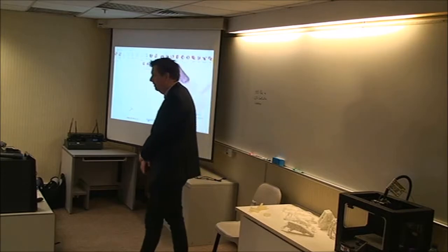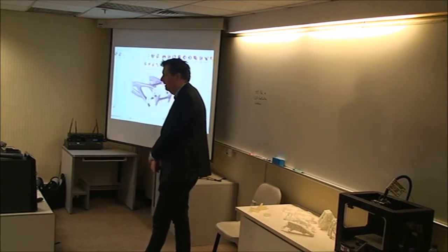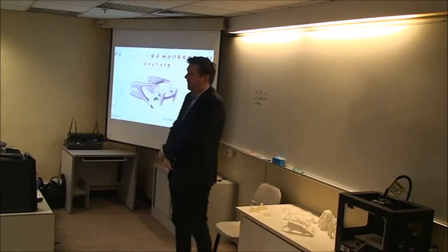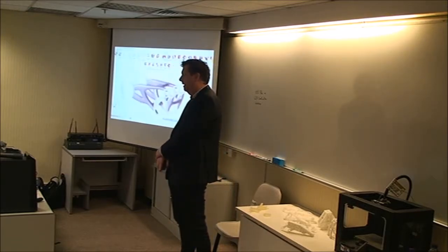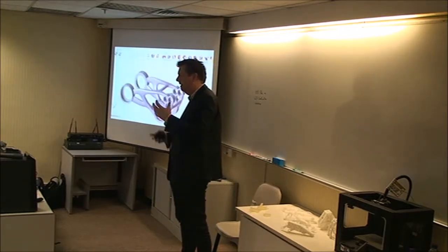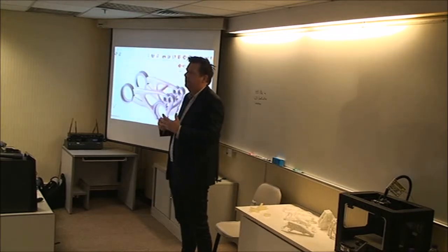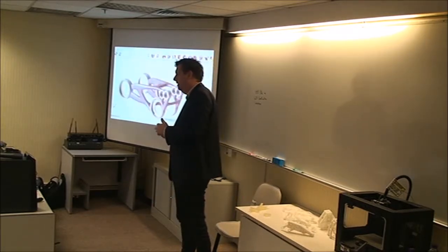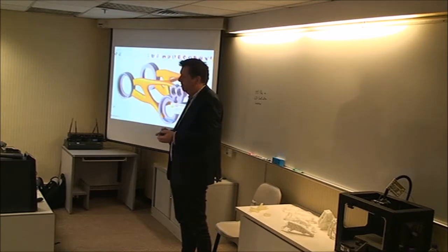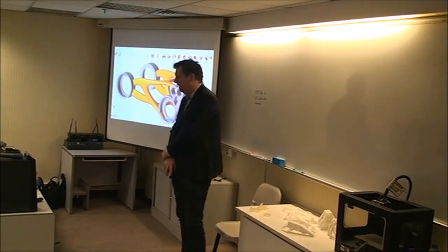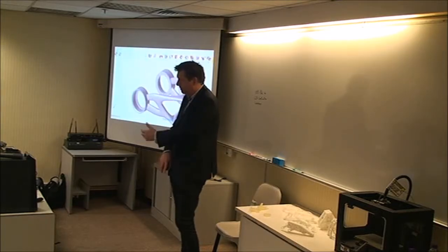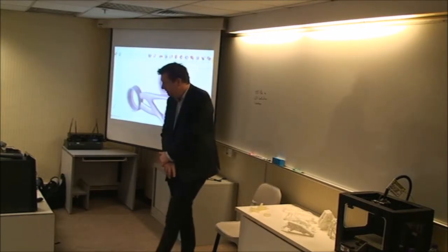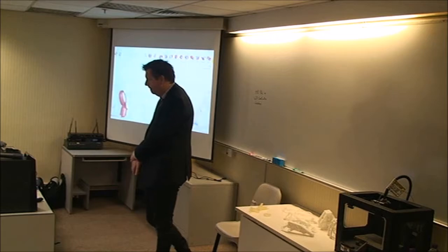I might fast forward through this one. 5 minutes later, you've got something that's looking pretty good. You still have to do some detailing, where your polymers join into your kind of regular prismatic kind of structures. You need to perform Boolean operations and put fillets around the corners and Boolean, that's the Boolean together. I think I'll do some filleting now.